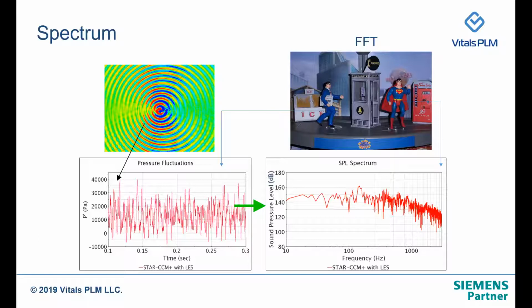But by looking at this random signal, it's very hard to comprehend any meaningful, insightful engineering quantity. But if you apply the Fourier transform and convert the time domain pressure signal into the frequency domain, we can have some meaningful insights. Once we do the FFT and convert from time domain to frequency domain, we can see the spectra associated with this random pressure signal.